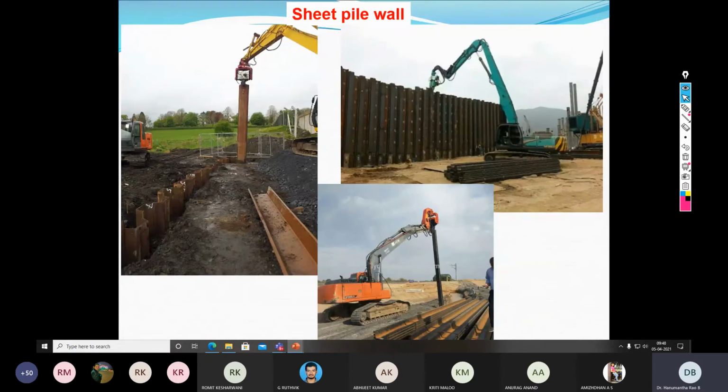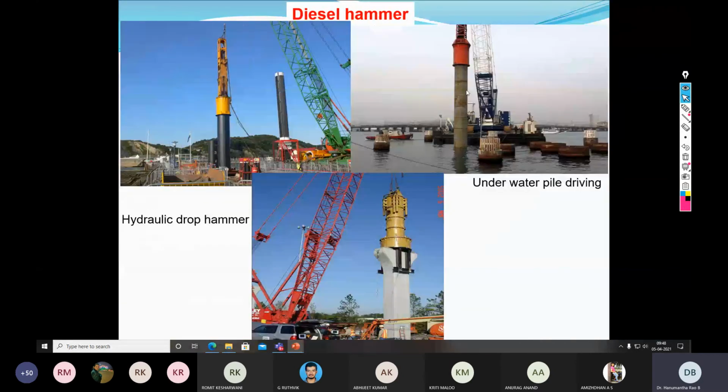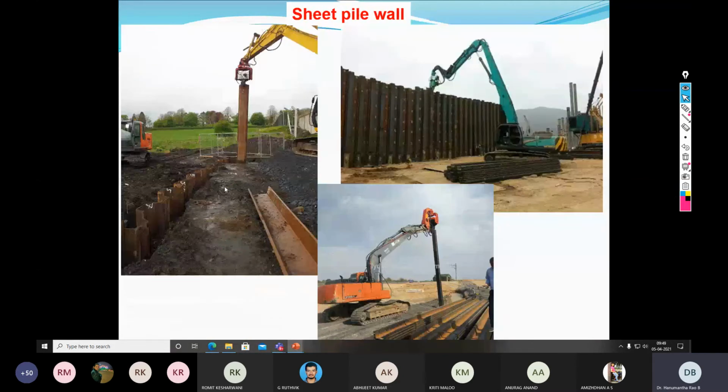So there is another kind of pile that is called as a sheet pile. In case of all previous discussions, if you look here, an isolated element is driven into the ground. A simple slender structural element is driven into the ground. But alternatively, suppose I take an H section pile, and a series of H section piles are driven one right adjacent to the another, such that the series makes some kind of barrier. That barrier is called as a sheet pile wall.